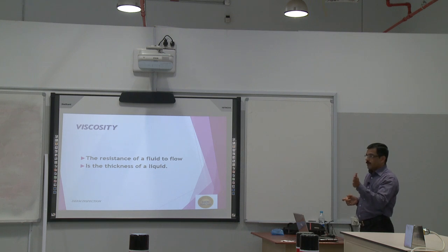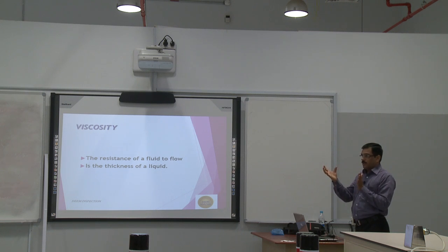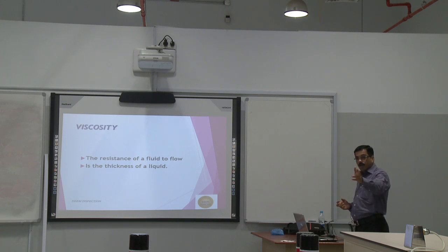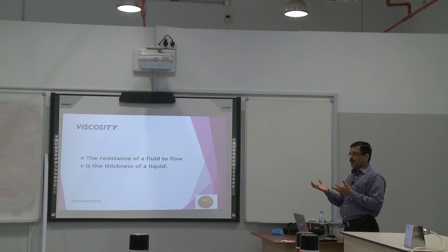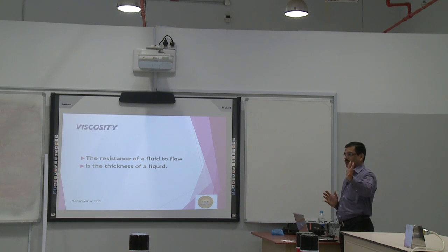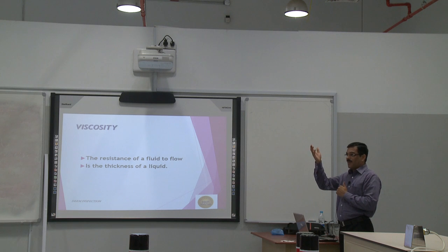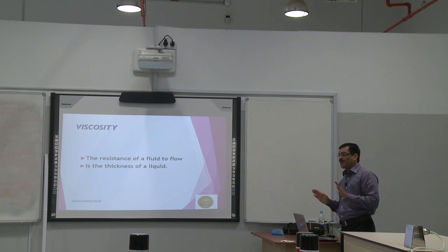I say 10 because if there is a white background, white will reflect 100%, let's say 97%. And this red penetrant has a reflection power of around 10%. So 97 divided by 10 is about 9.7 to 10. This is the contrast ratio we get with the penetrant material. If it were black, white to black would give a good contrast, but we have no black penetrant.